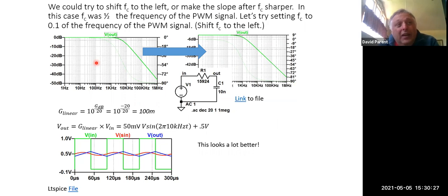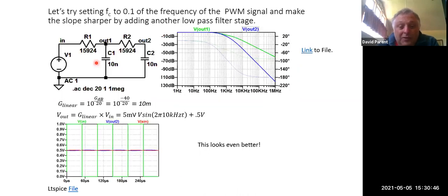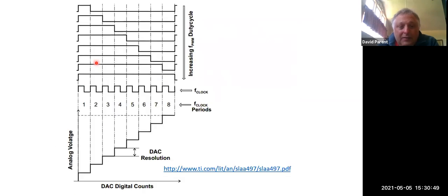Now, what's great is that the 50% duty cycle has the largest ripple. So if your ripple is 1 millivolt at 50%, all the other ripples will be smaller than that. So you actually only have to test 50%, which makes it really fast. Okay. So now here's a better picture. I'm on for an eighth, I'm on for 2/8, 50%.